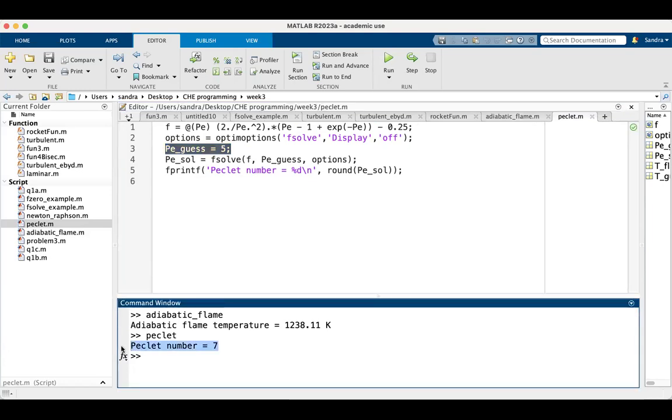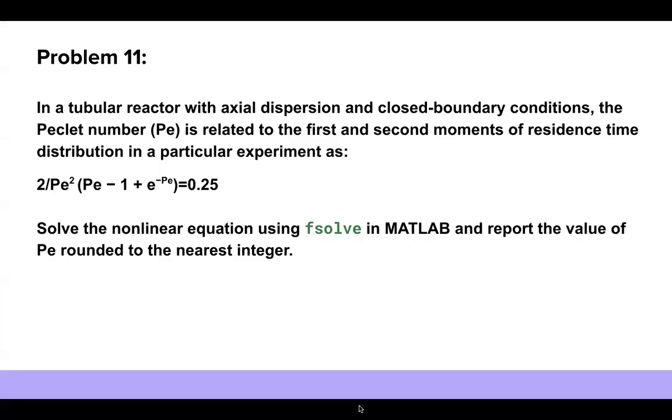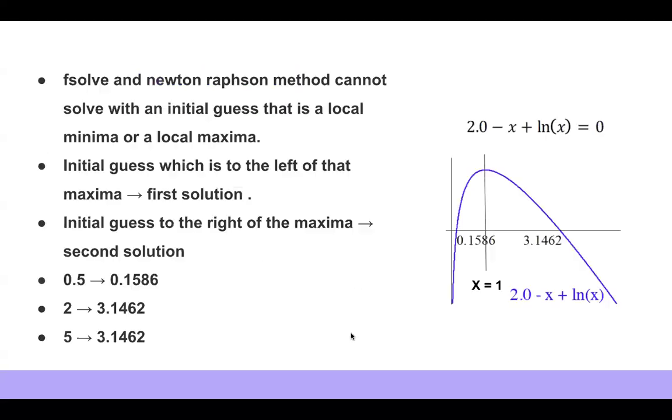Like this, while solving problems in the chemical engineering field or any field, you'll have several places where you'll have to solve nonlinear algebraic equations. It might not be very straightforward. Then you can use the MATLAB functions. Which functions did we see today? We saw fsolve, which has to be given an initial guess. Then we saw fzero, which has to be given a bracket in which the answer has to be found.